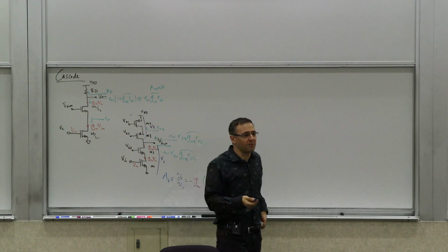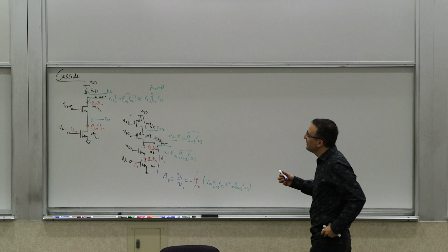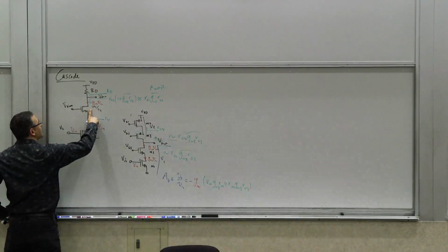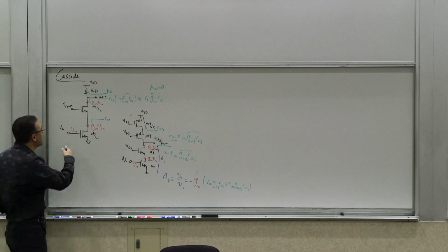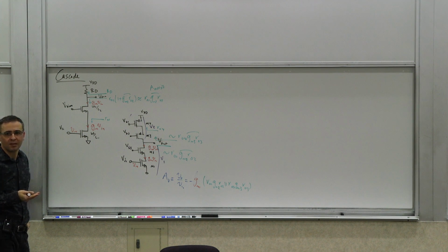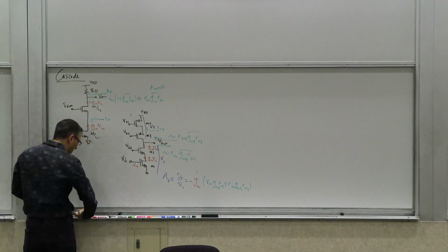How do we solve this problem? Can we think of a solution to this problem? Well, this concept even applies here, if you think about it. Because now you need more headroom for something like this as opposed to a single transistor. So how can this evolve into something that solves this problem? Yeah. Folded cascode, right? So what do we mean by folded cascode?